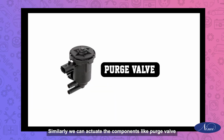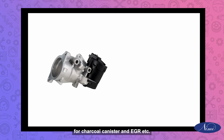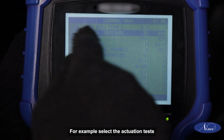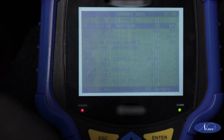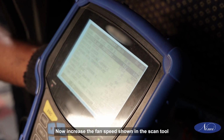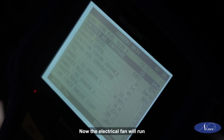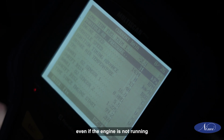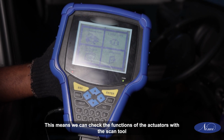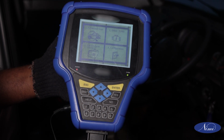Similarly, we can actuate components like the purge valve for the charcoal canister, EGR, etc. For example, select the actuation tests. Under this, select fan speed. Now, increase the fan speed shown in the scan tool. Now, the electrical fan will run even if the engine is not running. This means we can check the functions of the actuators with the scan tool.